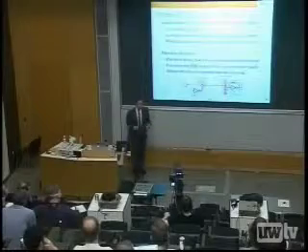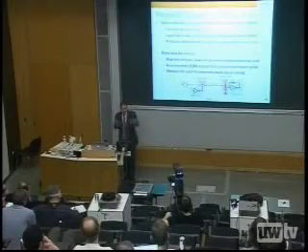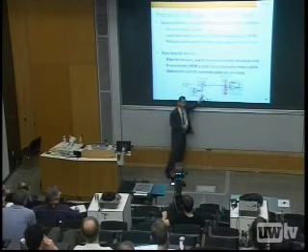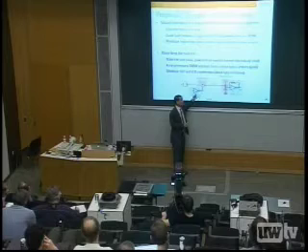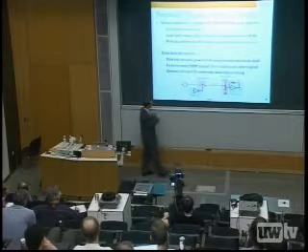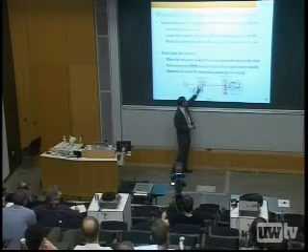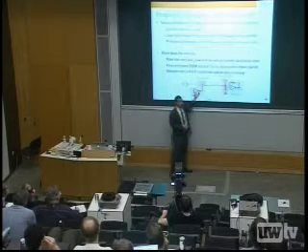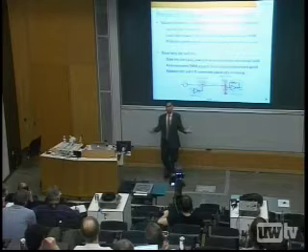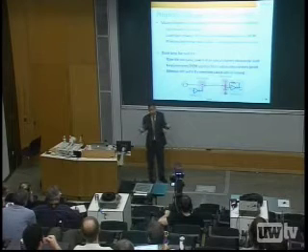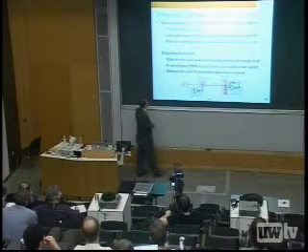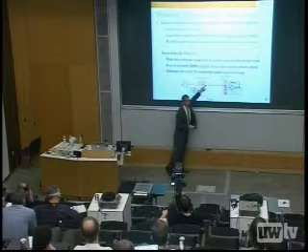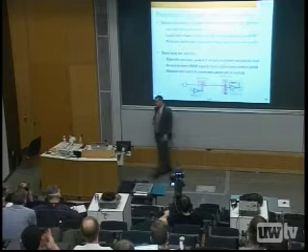If this is at all going to make sense, I better do at least 3 things. One is I better make the cost of this ridiculously small. I don't want to have this expensive at all. Number 2, I better try to separate any specialized optical processing, optical device, anything that's out of the ordinary from your standard logic or DRAM process, because you're not going to modify a DRAM process for photonics. And if at all possible, minimize the number of conversions from electrical to optical, just because they're going to cost energy.